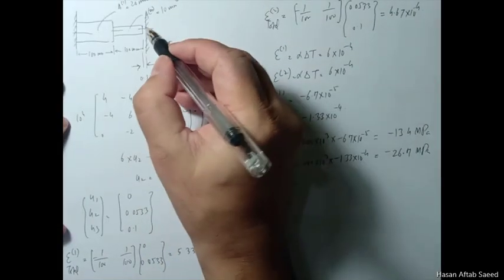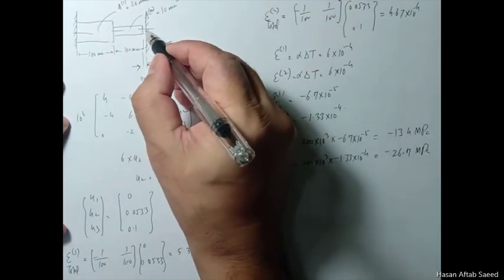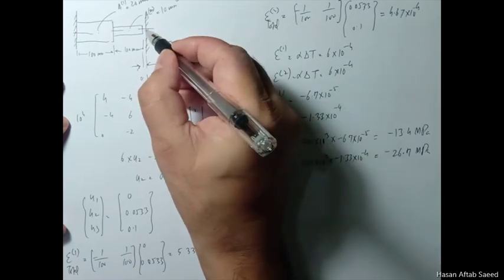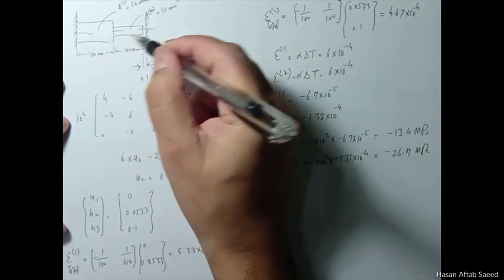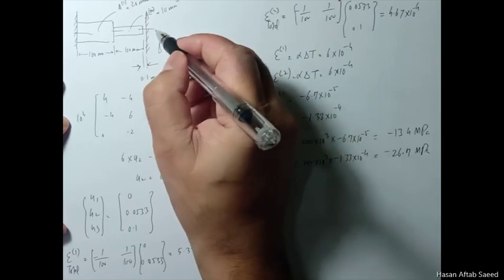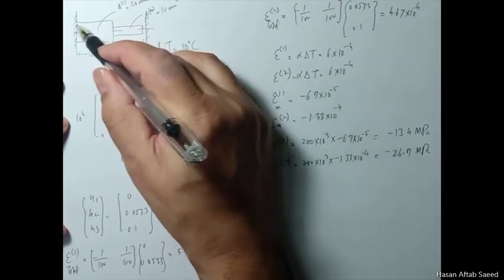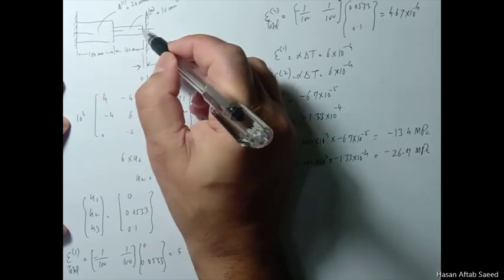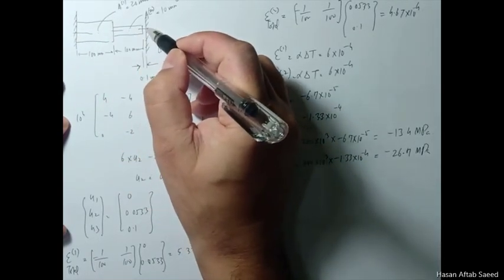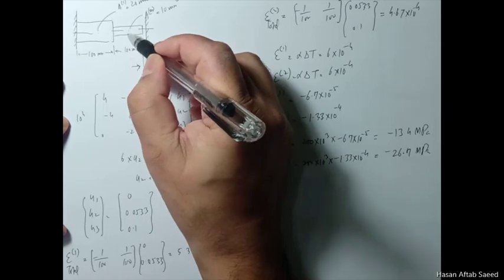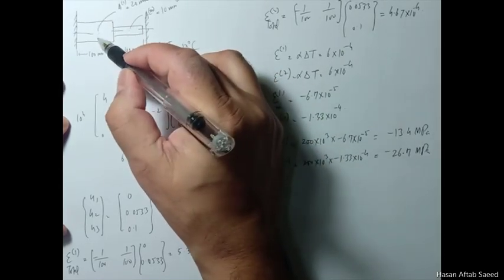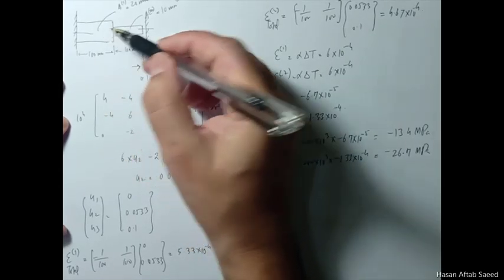How do I know this is double of that? Because at some point it would have touched it, and after that both walls would have pressed against these two. Now the force, because there are just 2 points of forces, this kind of force enters here and leaves there, so the force is constant throughout. So just that force, whatever that force is, divided by this area will give you stress here, and divided by this area will give you stress here. This area is half of this area.